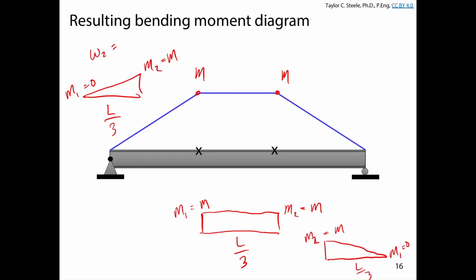What's omega 2 for the left-hand segment? We've done this twice now, right? 1.75. What does that do to the value of mu? It makes it bigger. What's omega 2 for the middle segment? We've done this already a couple times. It's 1.0. And over here, omega 2 is 1.75 also. Okay, so in terms of calculating mu, this one's going to have an mu value that's 75% bigger than this one, because omega 2 is 75% bigger. And likewise over here, it's going to have a higher value of mu.